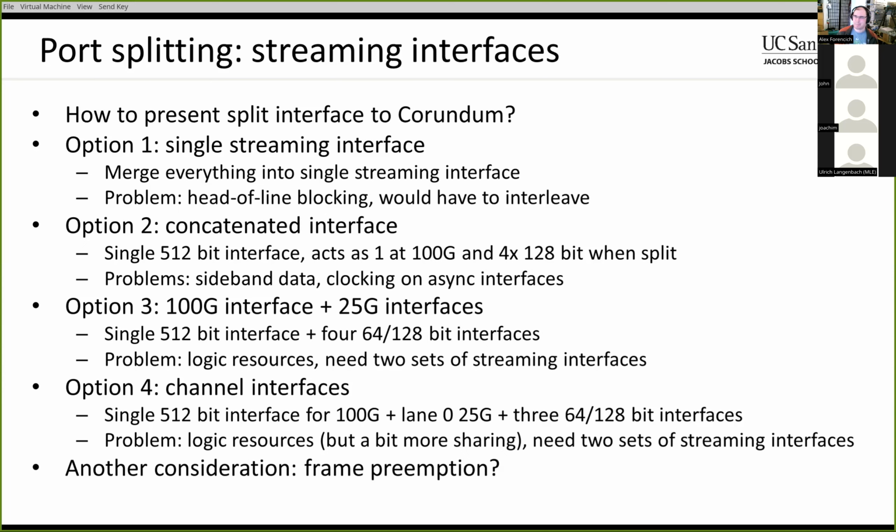I guess the IEEE description is more aiming at having 2 distinct interfaces. That's how they describe it, at least. Right, but I'm thinking, we can certainly do that. That would not be hard, but it's more about whether there's a way we can save on logic resources and buffering a little bit by putting these in the same buffer and following the same paths. But of course, it may just end up opening up too big of a can of worms to be worth it. Also, as a side note, do you know exactly what kind of restrictions there are on where the frame can be split? Because if you can split it anywhere, then that makes things annoying when you're operating at 10 gig or 25 gig with your 64-bit wide interfaces, versus if you can only split on 8-byte boundaries.